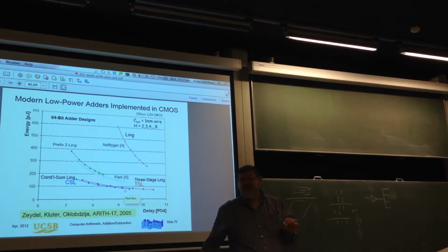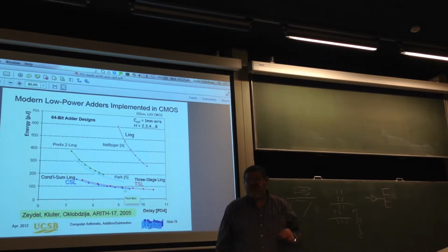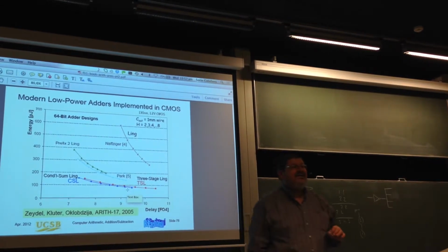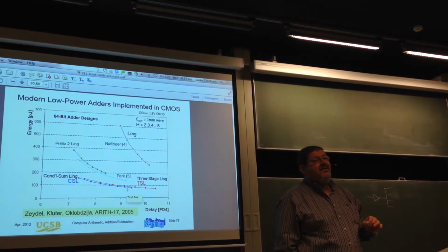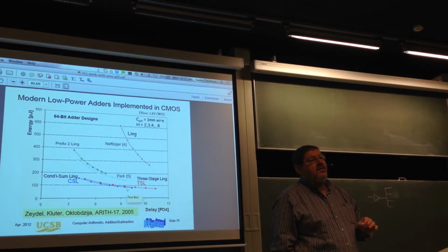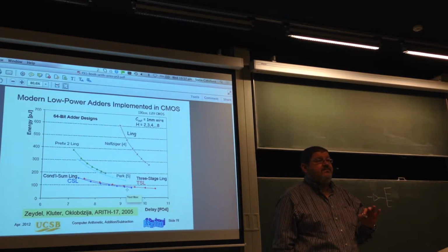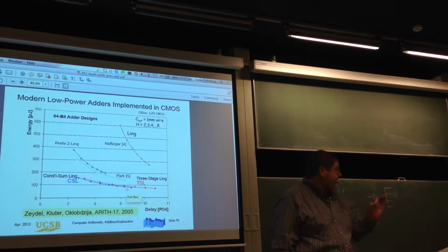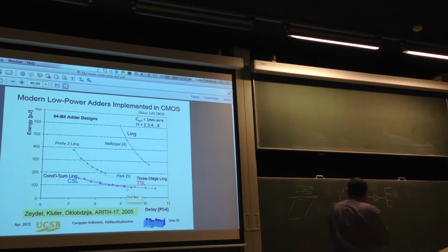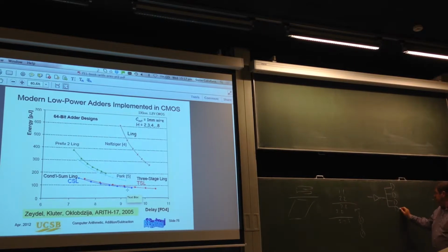You said that the inverter is driving a load of capacitors? Of 4 inputs, gate inputs. So each of the capacitors is over there that you've drawn. Well, I didn't draw them. Okay. Then essentially you assume that this is driving a gate, this is driving a gate, a gate. This is one of the inputs. So in total it's 4 gate capacitors that you have to drive.